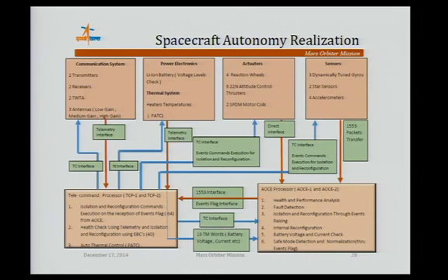This shows the spacecraft autonomy realization. You can see all the subsystems involved in the basic autonomy. The communication system is used to communicate to the ground, where there are TWTAs, which are high power dissipating elements depending upon the power condition. Judiciously they will be switched on and off depending upon the condition. And in power, the lithium-ion battery charge and discharge cycle control, and similarly emergency condition recovery, and telemetry parameters related to the battery and solar array will all be used for the logic.